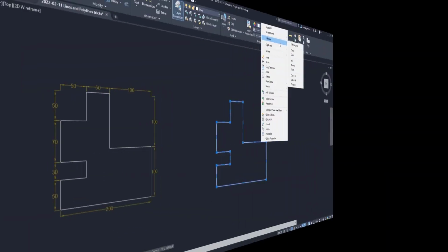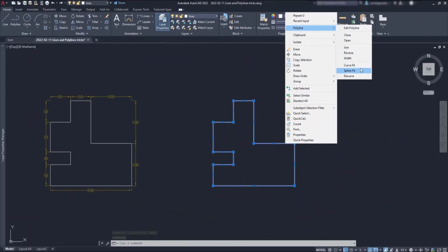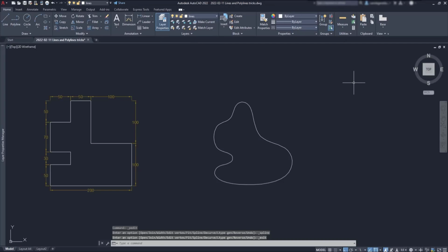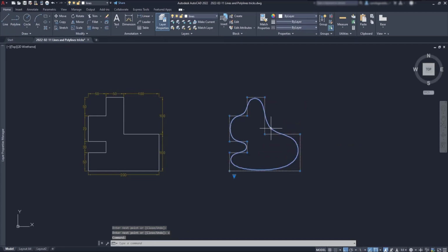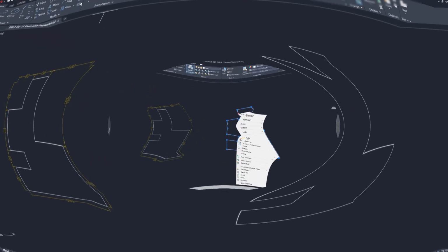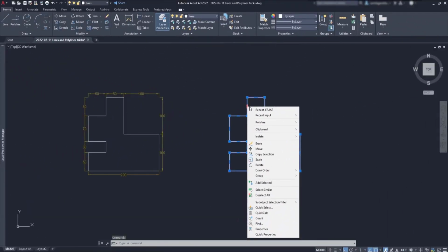On the other hand, if I convert a polyline to Spline Fit, it uses the method of drawing the Spline CV command. I know it sounds a bit counterintuitive, but CV actually means control vertices. In the same menu related with the polylines, we can add a width in case we want to represent that polyline a bit thicker comparing with the other objects in this drawing.